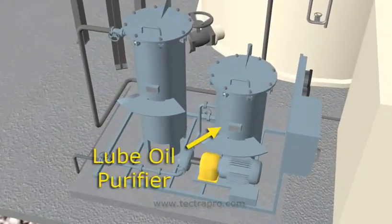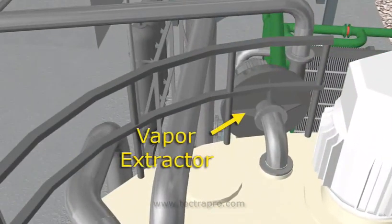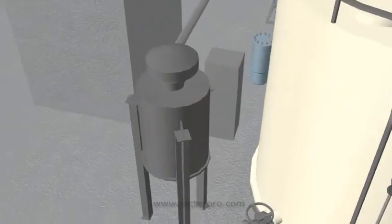The lube oil purifier unit is located to the east of the lube oil storage tank. The lube oil tank vapor extractor is located on the top of the lube oil storage tank. The vapor extractor exhausts through a mist separator which returns any entrained oil to the tank.